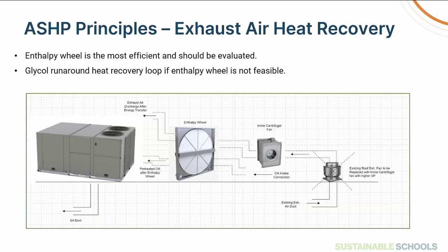But exhaust air heat recovery is obviously smaller than what the air source heat pump can do. Its real strength is it's working for you most during the coldest periods. So even though the direct economics, if we want to talk simple payback, we really have to be talking about electrification in terms of life cycle costing.